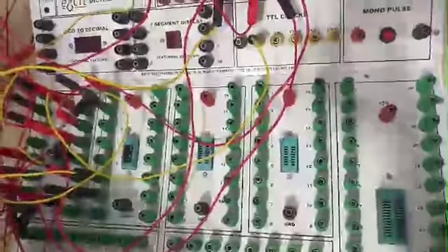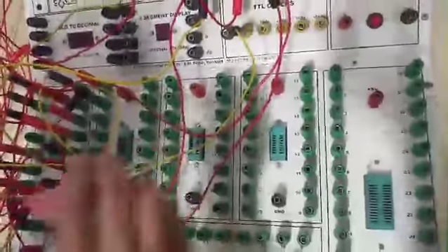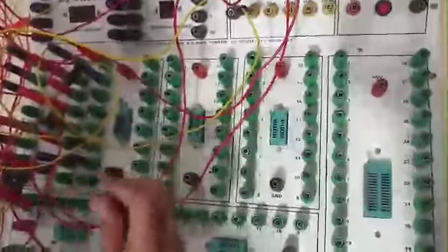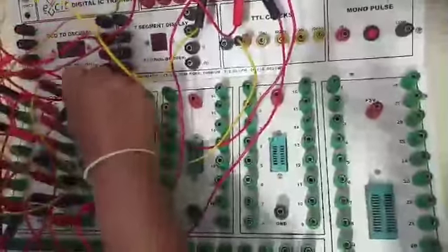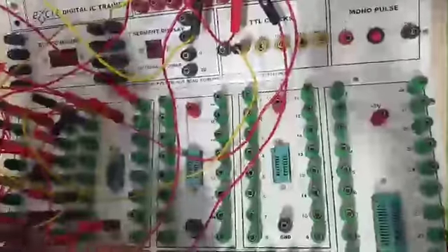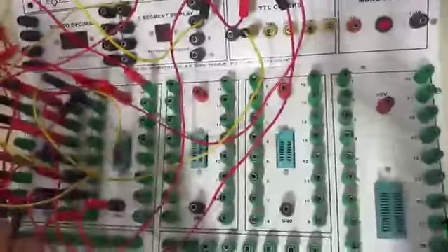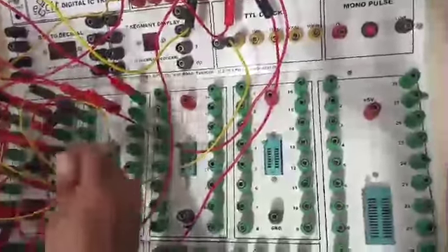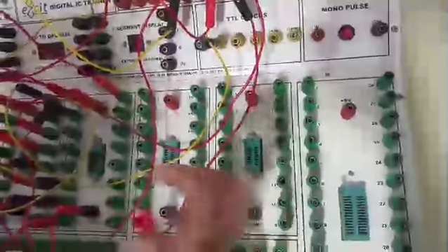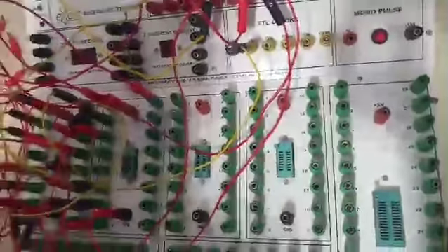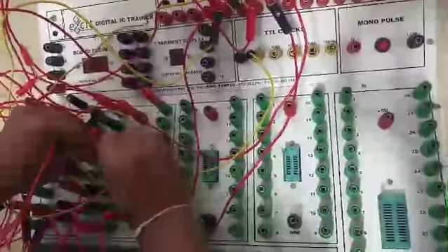Right. Now we have to give VCC and ground for the 7 segment IC. In this, pin number 8 is ground, and 16 is VCC, since it is a 16 pin IC. To make this work as a 7 segment driver, we have to short pins 3, 4 and 5, and give them to high voltage.